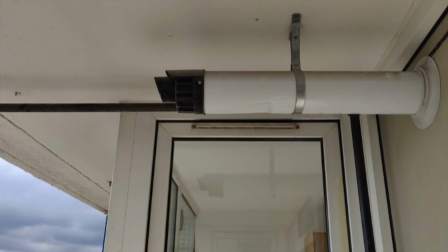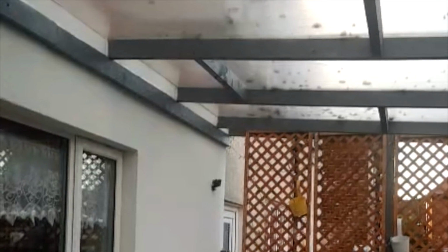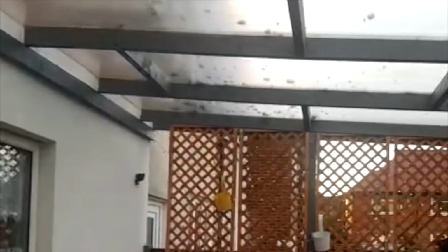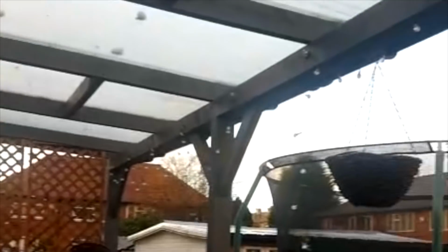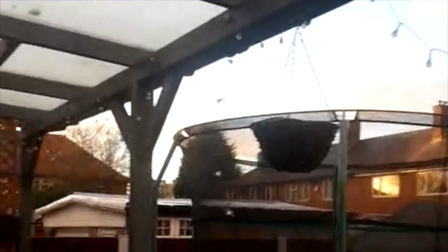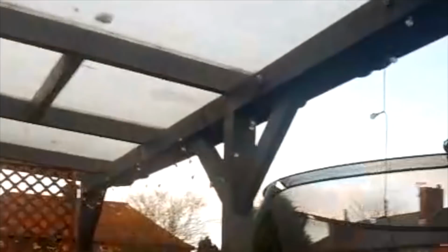What can you say? Now this flue is under some kind of covered patio, and it is 1200mm away from those patio doors, and this is open on 3 sides, even if it has got this bit of trellis here, and the flue is actually more than 200 down from the roof part, but the air intake part for this flue is actually half in the wall. So again, we will be classing this as at risk.